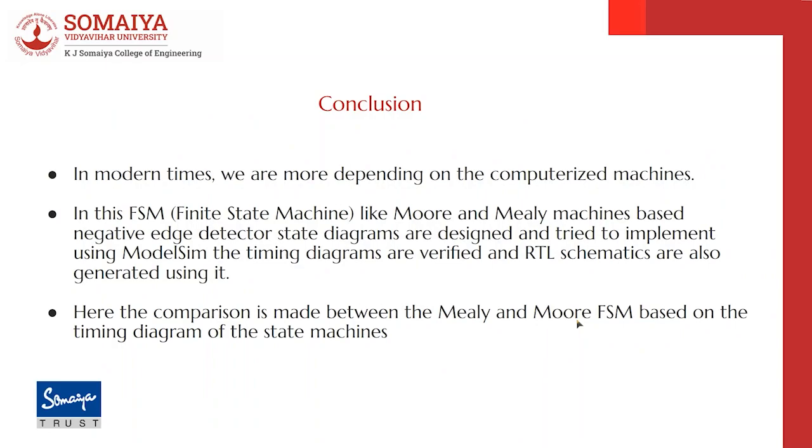Conclusion: in modern times, we are more dependent on computerized machines. In this paper, finite state machines like Moore and Mealy machine based negative edge detector state diagrams are designed and implemented using ModelSim. The timing diagrams are verified and RTL schematics are also generated using it. Here the comparison is made between Mealy and Moore finite state machines based on the timing diagrams of the state machines.